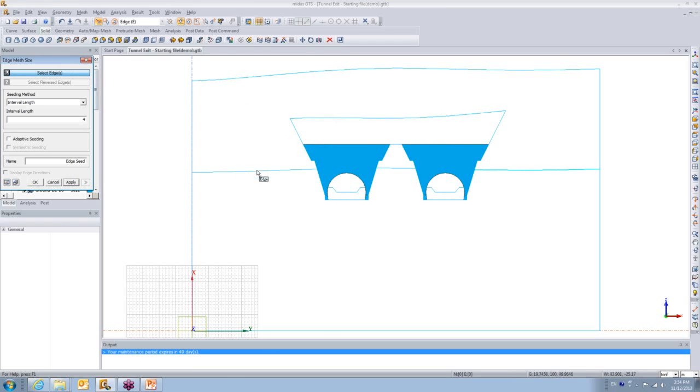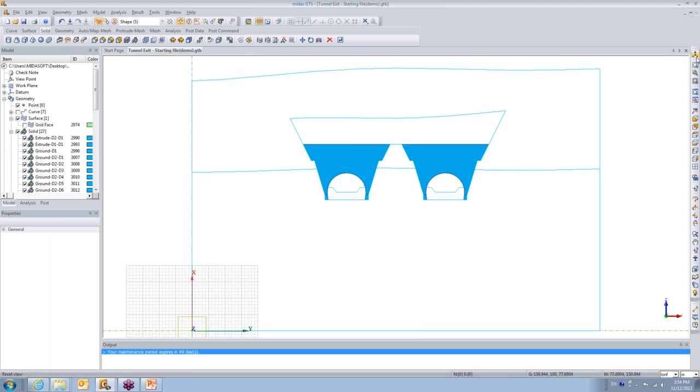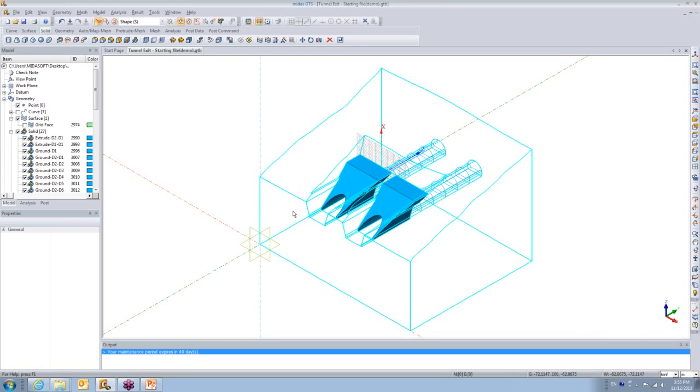And there is another way of controlling the mesh size. Let's say I want to apply it as a linear gradient. So I'll select the edge, let's say this one, and the reverse edge as this one. In the starting, I want the divisions to be of length 10 units, and then towards the end it should go to 4. So if I hit the preview button, you can see the distances are higher here and they are getting denser towards the end. And then I can say OK. So internally, the program knows along these edges what mesh size it should obey.